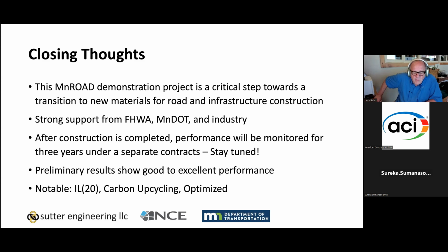It was placed very well, and again, that had 500 pounds of cementitious. So we got down to 500 pounds of cementitious, and it was probably one of the most workable mixes that we had. And then finally, the optimized mix, 501 pounds per cubic yard of total cementitious. All they did was take the standard MnDOT mix and optimize it. And they have a very, very well-performing mixture with a very low carbon footprint.